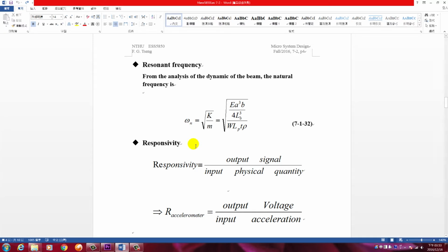When you want very high sensitivity sensing, usually we use a softer spring. A softer spring can give a larger displacement, more deflection and more strain. However, in that case, the frequency response will be sacrificed. The system will become slow. So it's not easy to design a system that is fast and also very sensitive at the same time. When you consider these two together, there is some contradiction.